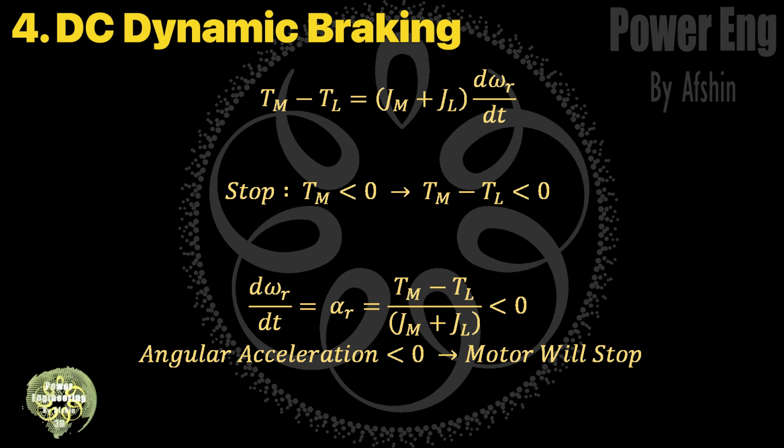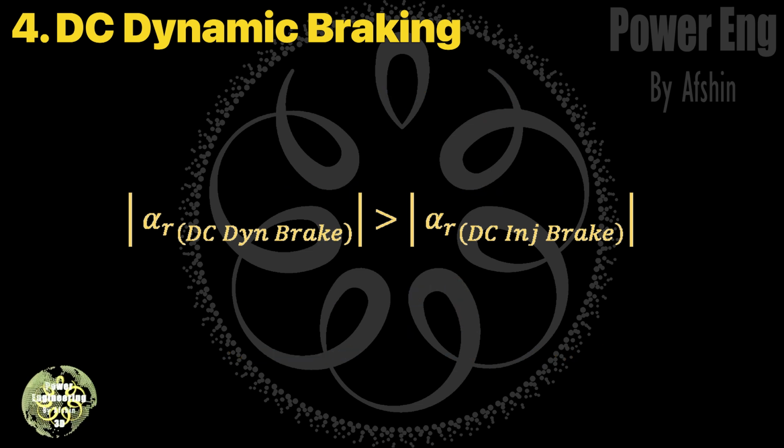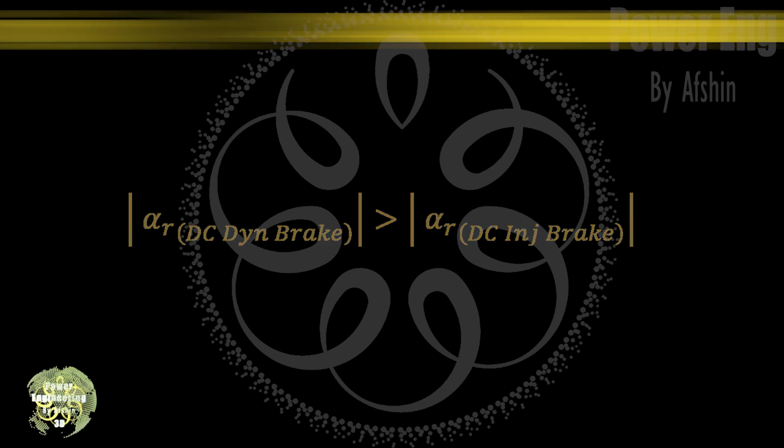One question you might have is whether the DC link capacitor is essential for this braking method. Share your thoughts in the comments. In this method, both the motor torque and load torque are negative, resulting in significant negative angular acceleration.